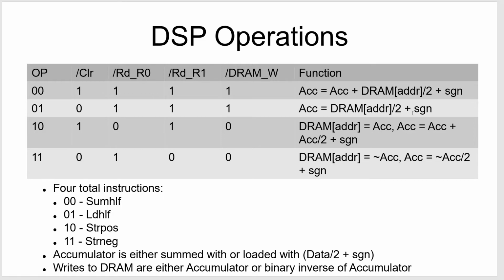First you'll see a load accumulator, then you'll do multiple copies of this where it simply adds over and over and over again to do a quote multiply, and then when it's finished it saves it, and this is called the store. We call it store positive and store negative, and the difference is whether you write to register R0 or R1, because one of them has that inverted output and one does not.